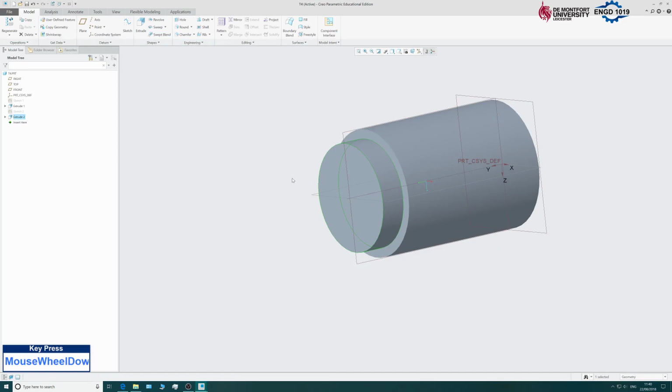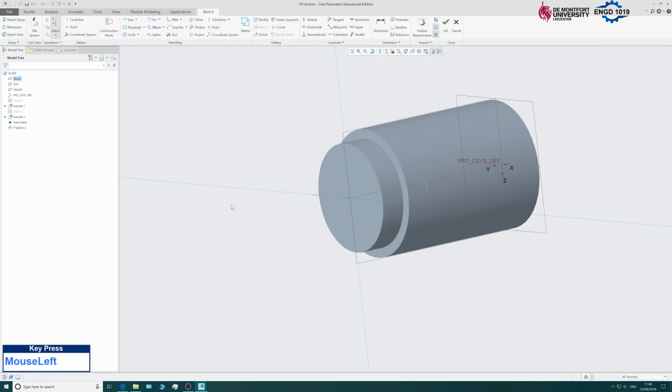Okay, so on the drawing there's now a slope section. What I'm going to do is add that in afterwards, so I'll just build this next cylinder using the slope and the normal cylindrical section. So we go sketch, click on the face.